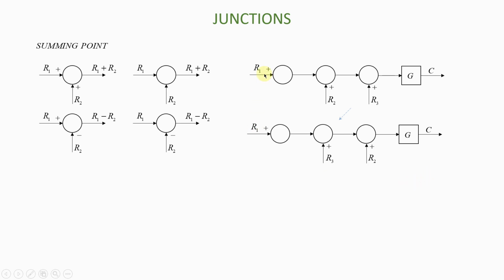And also, it is important to not always have unnecessary numbers of summing points. In this case, for instance, you could add the three signals on just one summing point. So it could have been like that. And so what you see here is equivalent to this, and it is also equivalent to that. Okay, so it's very important for you to understand that. And so having said that, this is what you need to know about summing points.